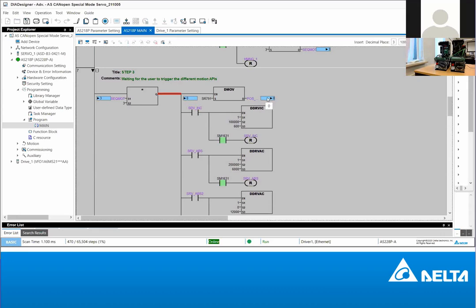And then you see here, the feedback, the current position will be 100,000. So let us try. I want to turn it on. Watch the shaft in the video. You will see it rotate slightly to position 100,000. You can see it's moving. It has gotten there. And you see this flag is a feedback flag. This flag tells us that the incremental movement command has been initiated and is completed. And this is the current position of my shaft: 100,000.